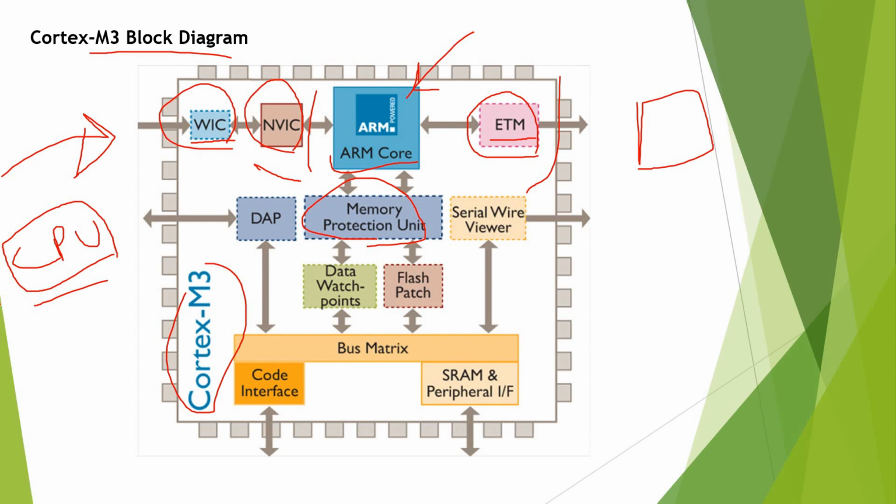As I said, those blocks are optional, so we may have a Cortex-M3 in another product that doesn't implement these features. Then, besides those optional ones, we have must-haves, like the NVIC. The NVIC in the Cortex-M3 is responsible for managing the different interrupt signals going to the core. NVIC stands for Nested Vector Interrupt Controller. For example, it defines the priority for each interrupt signal, enables and disables each interrupt line, groups the interrupts per priority or per group of priority, and has many other functionalities.